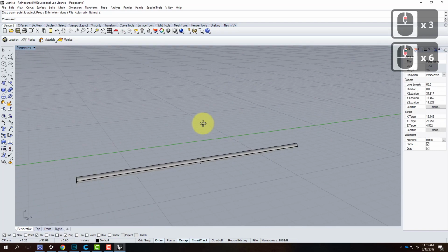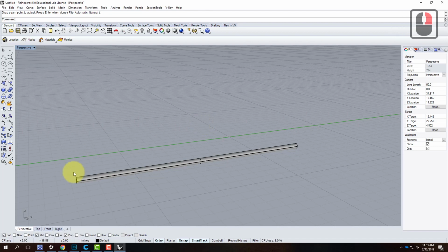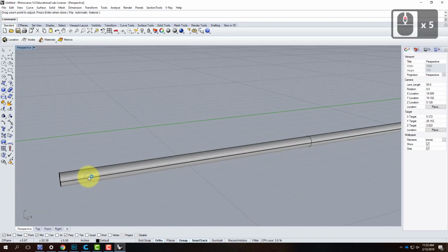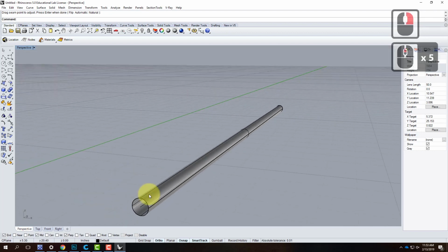Right, like that. Yeah? Does it just default to like a selected thickness? This is infinitely thin, actually. Okay. So it's not a solid, it's just a thin little shell. That's the way Rhino models everything, even if it is a, quote, solid object. So if I made this with a cylinder, for example, it would act like it was a solid object, but it's really not. It's just a set of surfaces that define an area inside and outside.